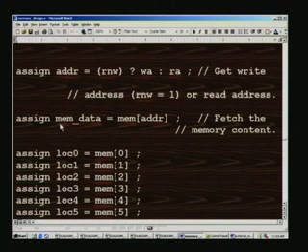And we have another variable or signal rather called memory data, and this is nothing other than reading that regmem. So that memory is being read here with the address as ADDR, and this address would depend upon R and W. It could be a write address or read address, and fetch the memory content. That is what it says here.